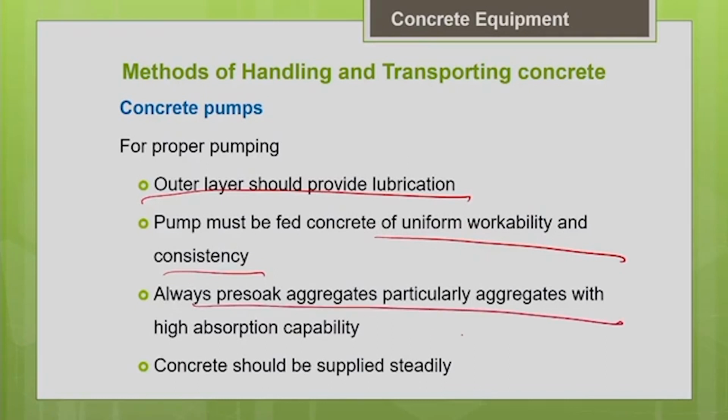More of the mixed water will be absorbed by the aggregates. So what will happen is the workability or the pumpability of the concrete will get severely affected. In that case, what you are supposed to do before pumping is the pre-conditioning of the aggregates. That means you pre-soak the aggregates so that they will absorb the water well.